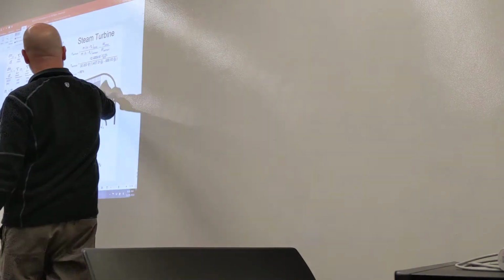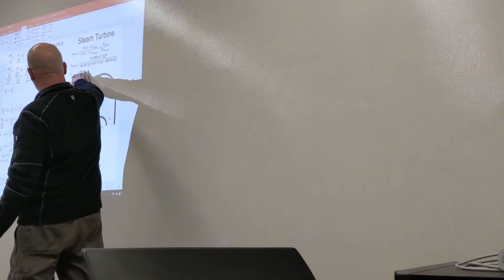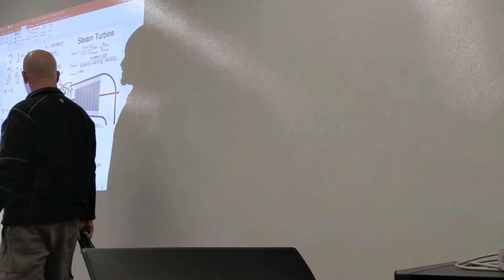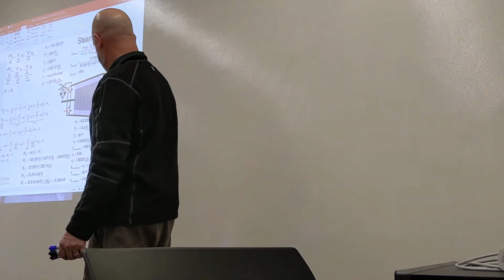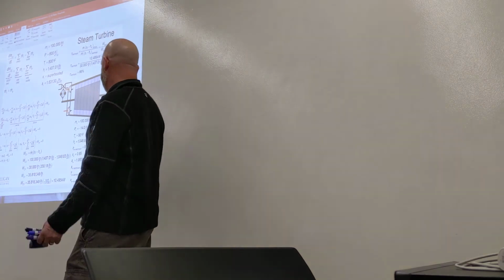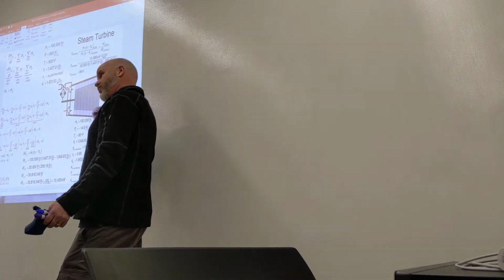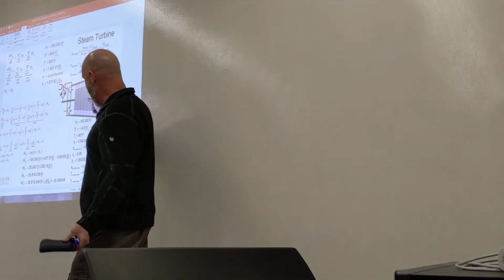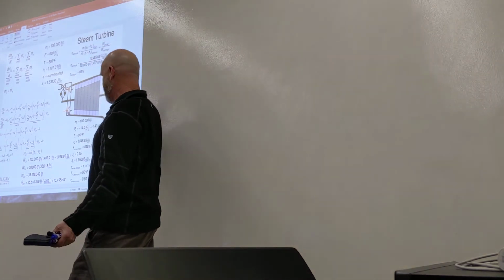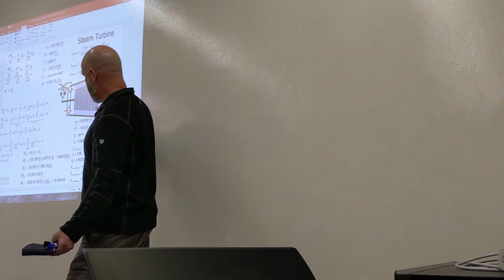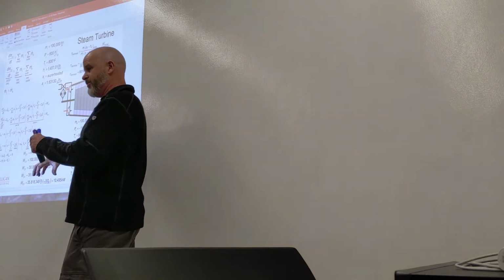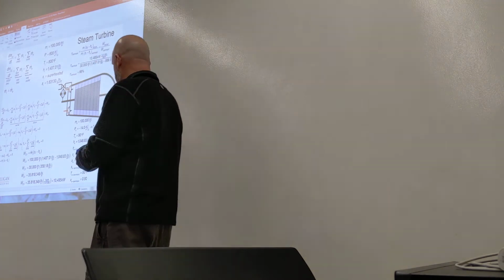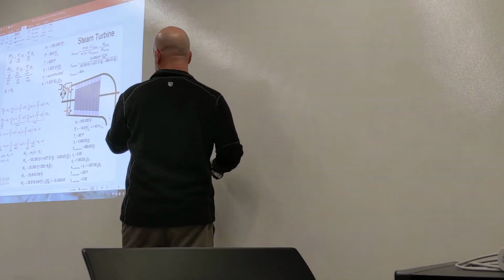With this one, I got an isentropic efficiency of 66%. So I think we were 850 today. Yeah, 850. These are not the same numbers, but working through finding enthalpy at the exit of the turbine, using the power generated by the turbine shaft, the equation we have here, then you can know the enthalpy of the steam coming into the condenser, and you can know delta H for the condenser.